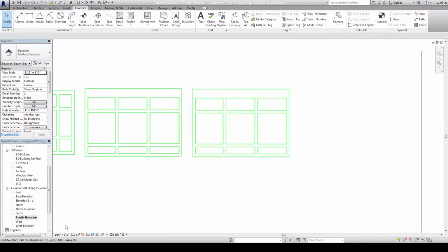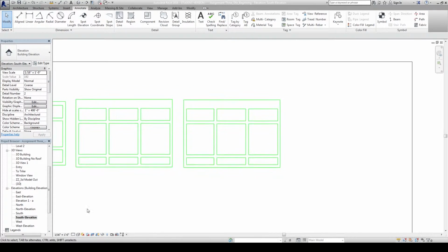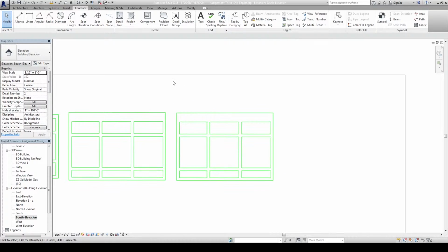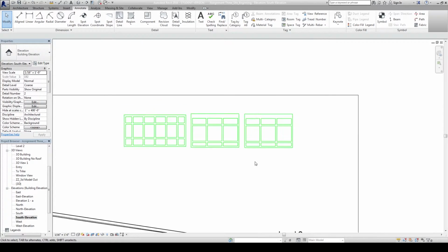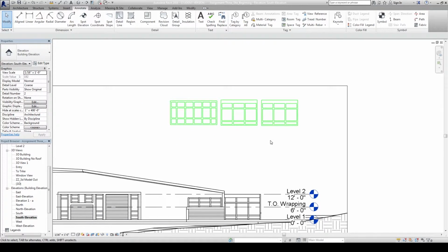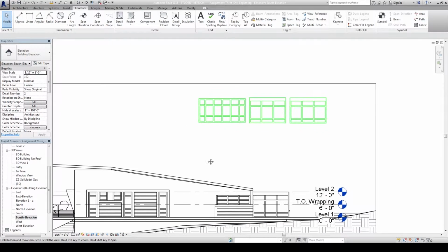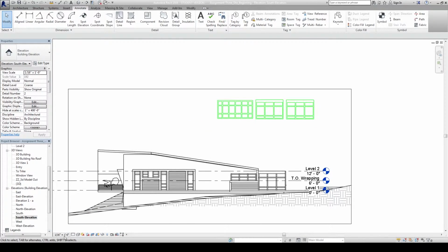So this is at a 16th inch scale in terms of the representation, but this is also at 1:1. If I do a quick dimension out to out on these edges, you can see this is a 17-foot piece. Always work on these things at that 1:1 scale, because if I ever decide that my model needs to be at a 32nd of an inch, 1:20, 1/8, anything along those lines, I can simply change my scale here, resend the output, and I'm ready to go.